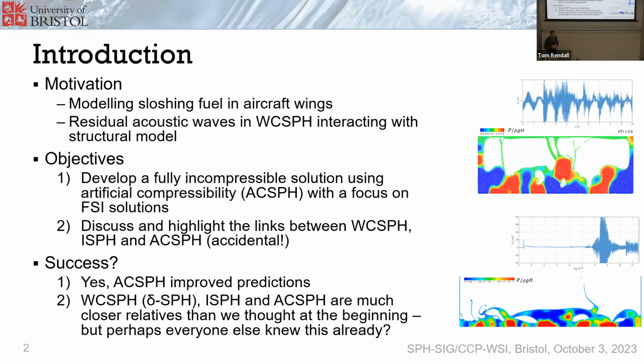And during aircraft design, that's an important parameter because the level of damping that you can assume has implications for the level of conservatism in the design. So if you have a higher level of damping, or you can prove a higher level of overall damping, you can potentially save weight on other parts of the aircraft structure. So the whole objective of the project really is to try and understand that physical behavior and utilize it to justify an assumed level of damping for analysis by the manufacturer.